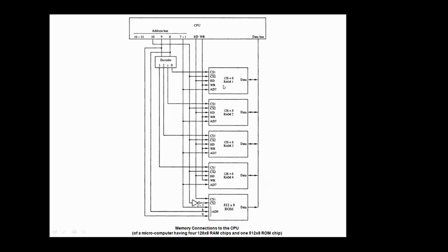If the CPU says address, for example, 7 in terms of decimal, we don't know which 7, the 7 of RAM 1 or 2 or 3 or 4. To clarify this thing, we need extra 2 bits, because we have 4 RAMs. To distinguish between 4 things, we need 2 bits.